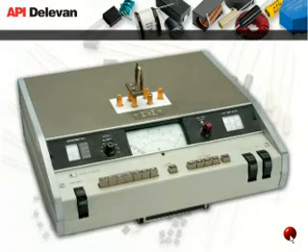Q meters such as HP 4342A or 260A measure Q by direct reading. Meters including the HP 4191 and HP 4291, 4285, and 4275 read Q as a comparative measurement. The purest and most accurate way to measure Q is with a direct reading Q meter and not on an LCR meter or on a comparative type of bridge.